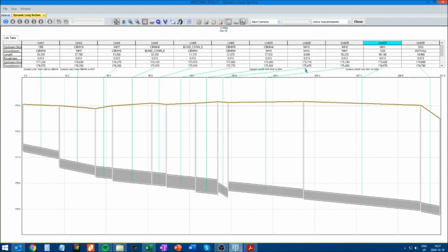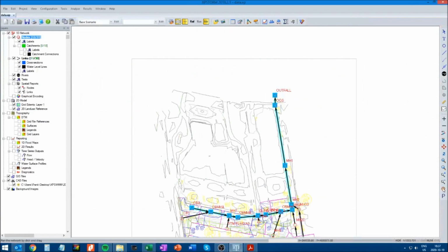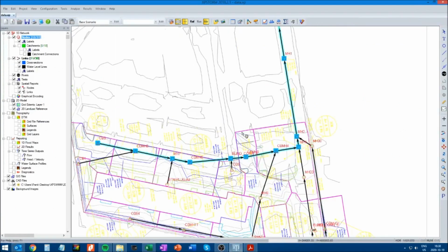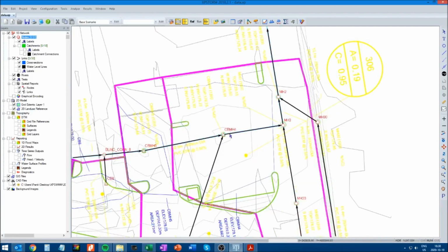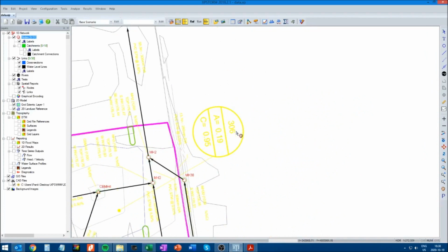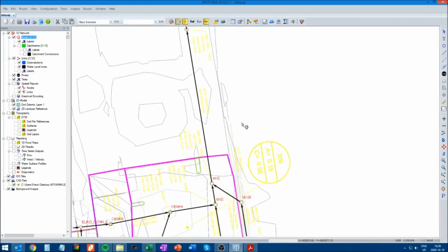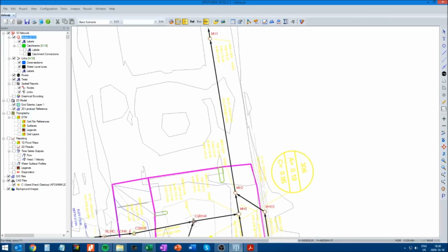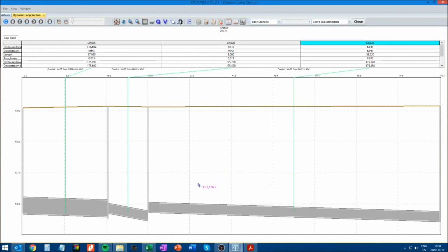It is link 26 from manhole 3 to manhole 2. So it's over here. Let's see what the issue is. I'm just gonna select the shorter reach. Let's go from this point to that point. That's what the problem is. Okay, so there's something wrong with the pipe inverts.